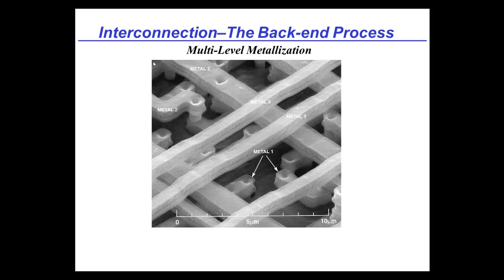This is what's cool about the integrated circuit. You're going to get your wafer and manufacture your transistors, and again, as I've said a number of times, we're going to show you a baby version of the process in a minute. But after you do this, you then also manufacture all the wires at the same time. You manufacture all the patterns that will connect all of your transistors, making all the wire connections you need. Think about your breadboard. You put in your resistors and transistors and little packages, and then you sit there with the wires and connect them one by one. This will drop connections for hundreds of millions of transistors all at the same time, at multiple levels, with sort of hierarchical design choices. Pretty neat.